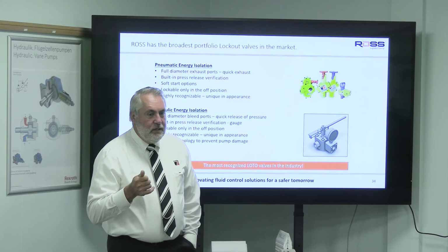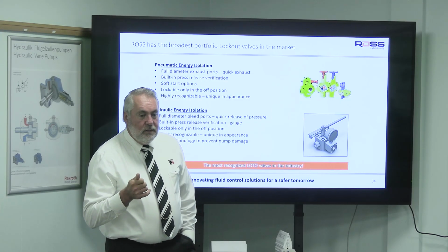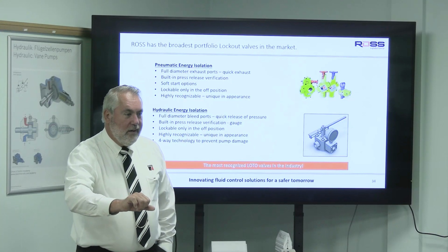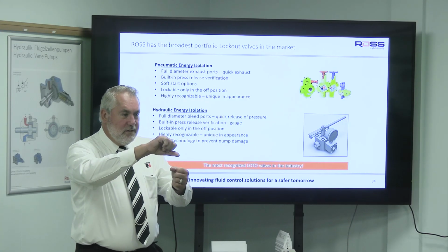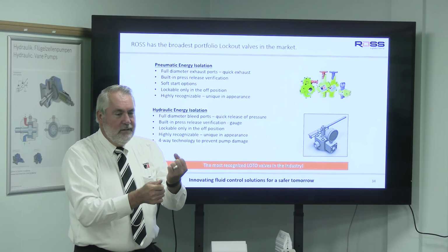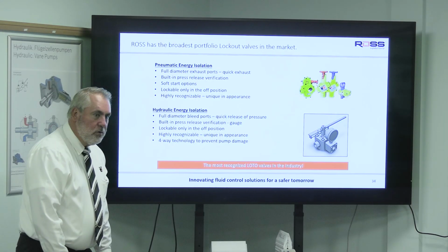And if you read even the ISO 14118 standard, it says a single deliberate action for lockout. Most of your ball valves out there have one handle for blocking the supply and one for bleeding it. It's not compliant. It doesn't meet the requirements.